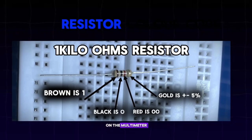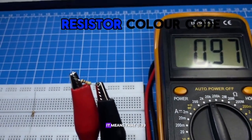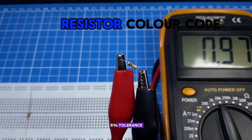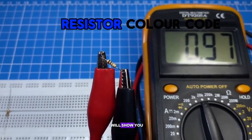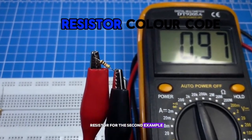As you can see on the multimeter, it is showing 0.97 kilo ohms. It means that 0.03 kilo ohms is the 5% tolerance, which is minus. This is just example 1, and for you to better understand it yourself, I will show you one more example. So let's use this resistor for the second example.